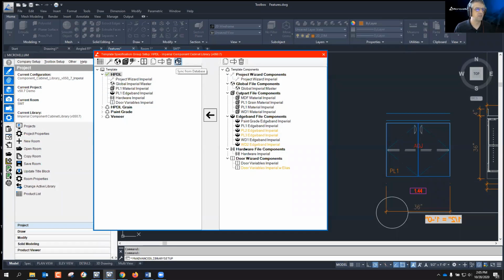This also forces it to reinitialize. So if you're doing a whole bunch of stuff and you're suspecting a refresh issue, that's what this is for. You can click that. I can think of another example: if you delete a bunch of materials, it might delete them out of this spec group, but maybe it didn't delete them out of the other spec groups. And so that's what this does. It goes through all the spec groups and makes sure everything's sorted. So this is a really nice little button when you're trying to do some housecleaning for your materials.